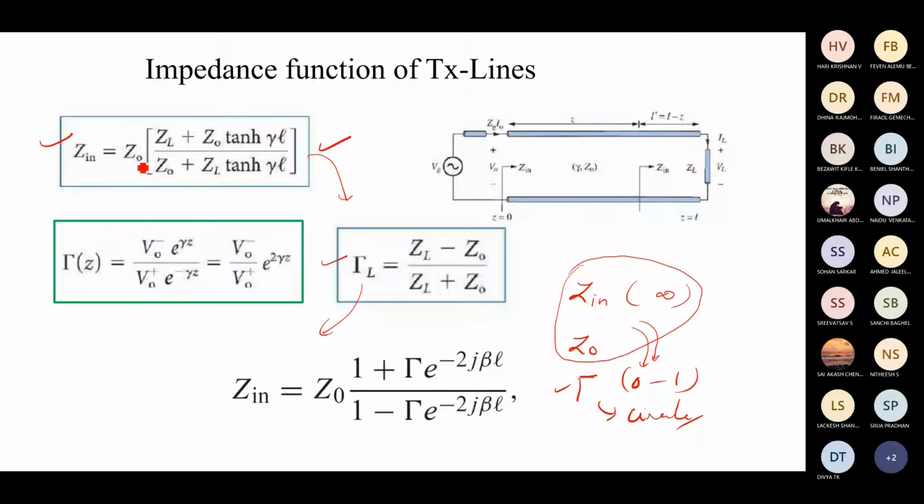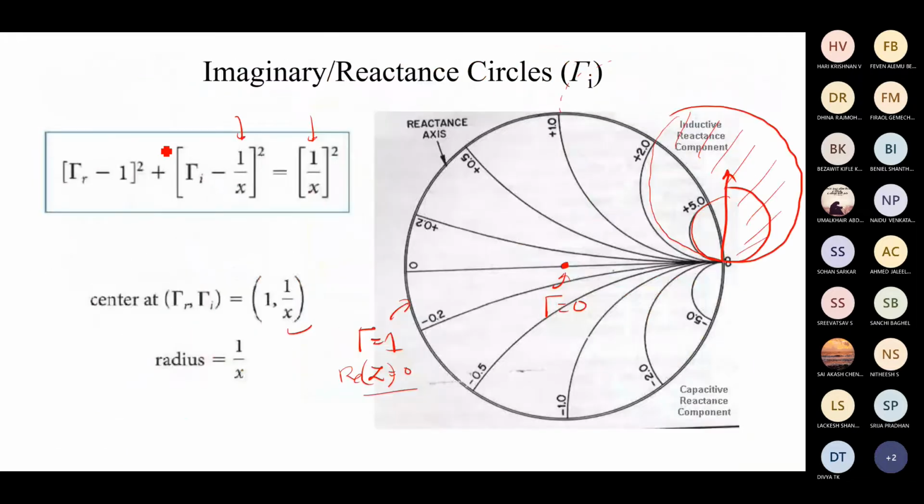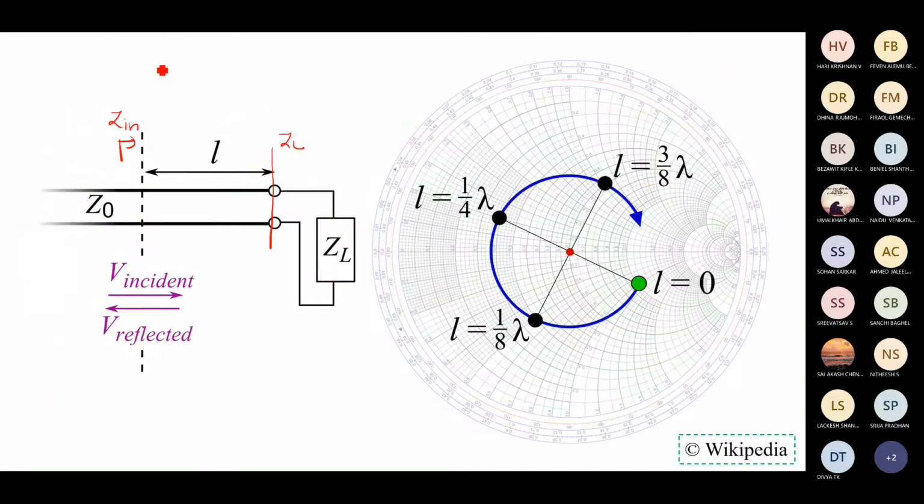The input impedance is nothing but, let me write it, Zin equals Z0 times (ZL plus j Z0 tan beta L) divided by (Z0 plus j ZL tan beta L). With respect to this equation, at any particular length we can calculate that. So instead of applying this slightly complicated equation every time with beta and all, we can move along the Smith chart itself.